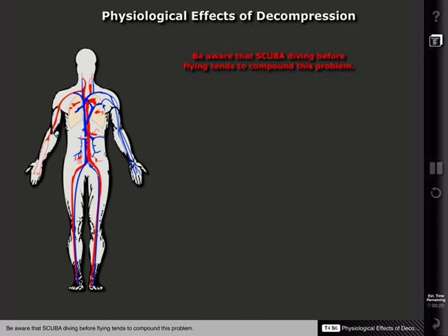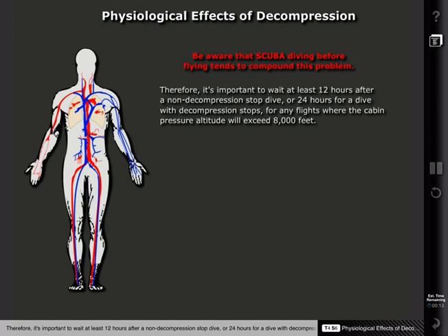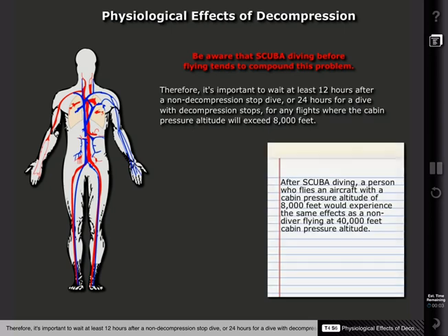Be aware that scuba diving before flying tends to compound this problem. Therefore, it's important to wait at least 12 hours after a non-compression stop dive, or 24 hours for a dive with decompression stops, for any flights where the cabin pressure altitude will exceed 8,000 feet.